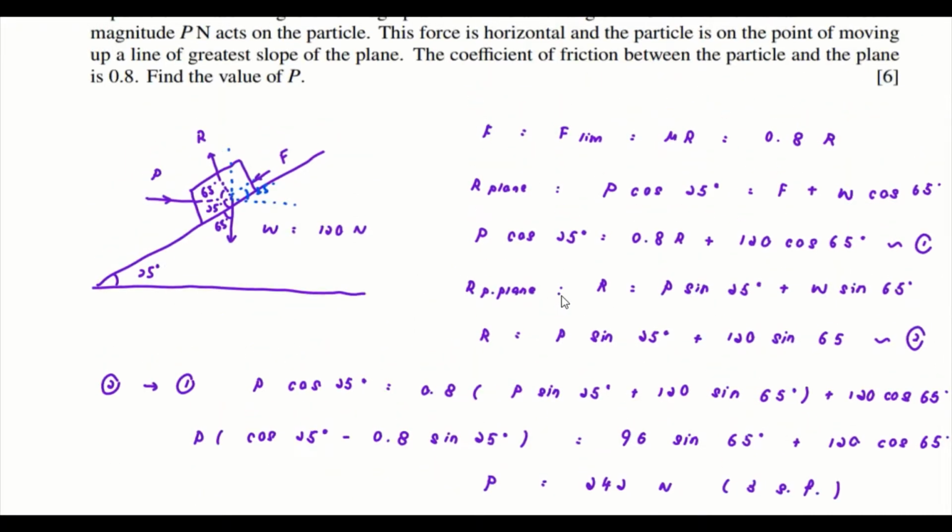What is important is the force diagram, and that you are not confused by where the line is drawn, so you resolve it in that direction. The idea is that it depends on the arrow. It's a force that acts like this, so when you resolve it, it should be going down and going this way. It's not because the line is here that you resolve it here and here. That's a totally wrong idea.